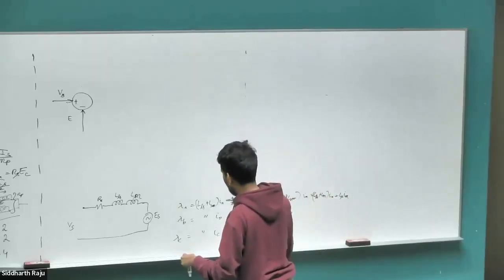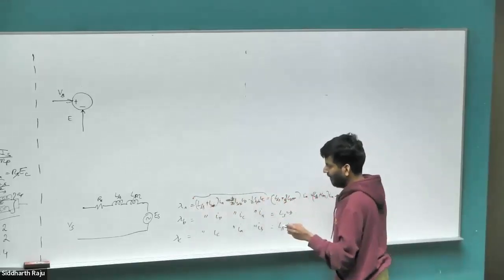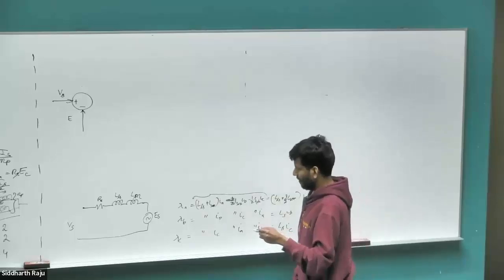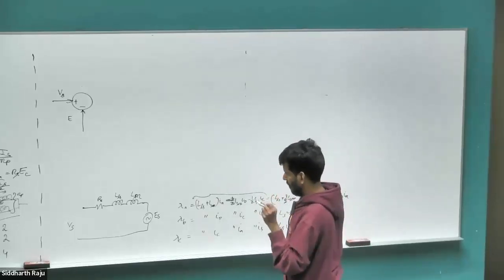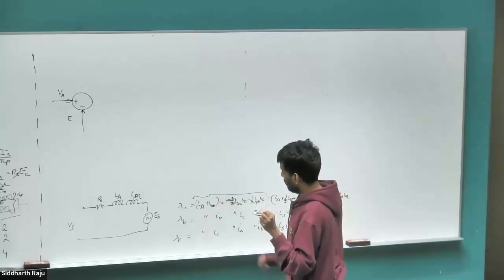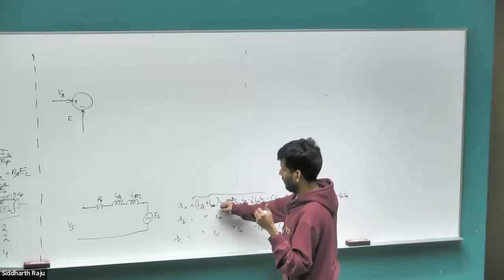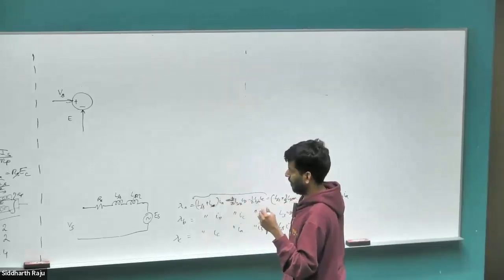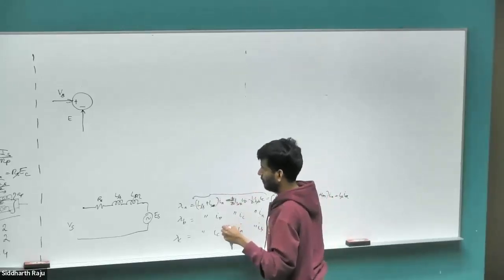So I'm going to retain this original form just because it looks pretty and we get to use a little bit of matrix. But there's another reason as well. When we do the induction motor model, in the extra lecture for induction motor, this model becomes quite helpful because the inductance of the rotor keeps changing, and putting it in this matrix form becomes quite helpful. When we go there, you get a 6 cross 6 matrix in that case.